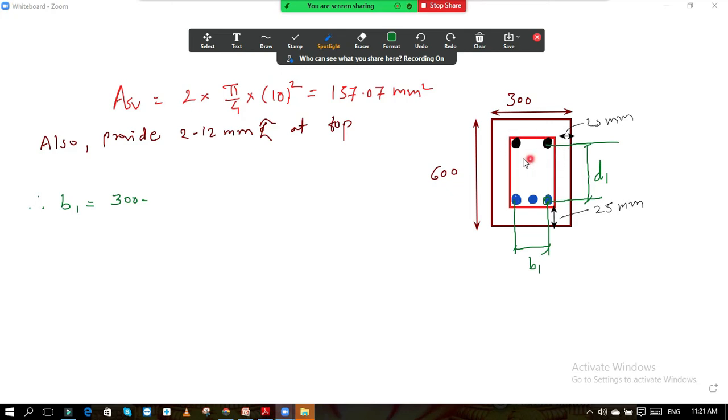So these bars, we have not designed these bars. Please understand this. We have provided these bars as per the norms given in the IS code for the earthquake resistance proof design. So either way, we have not designed these bars, the designed bars are these, 3 bars of 20 diameter. This is the first thing. Second thing is that this bar is having higher diameter, that is 20 which is greater than these 12. So that is why we are taking the width at these bars.